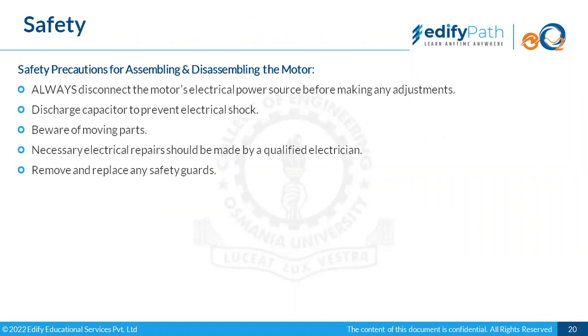Safety: if we talk about safety precautions for assembling and deassembling of a motor, always disconnect the motor's electrical power source before making any adjustments. So when we are deassembling the motor, or attending to the motor for overhauling or any maintenance issue, we should always disconnect the power source first, and only then attend to the motor. Discharge the capacitor to prevent electrical short. The capacitor should be properly discharged, because we know that a capacitor stores charge, so that we don't experience a shock.